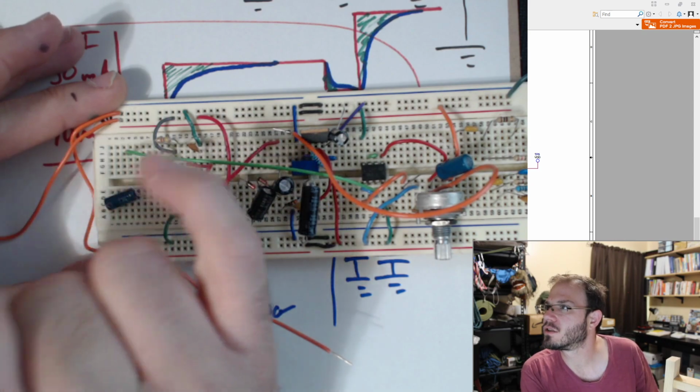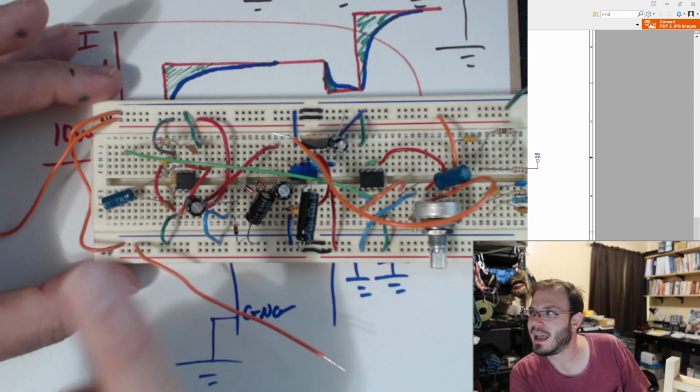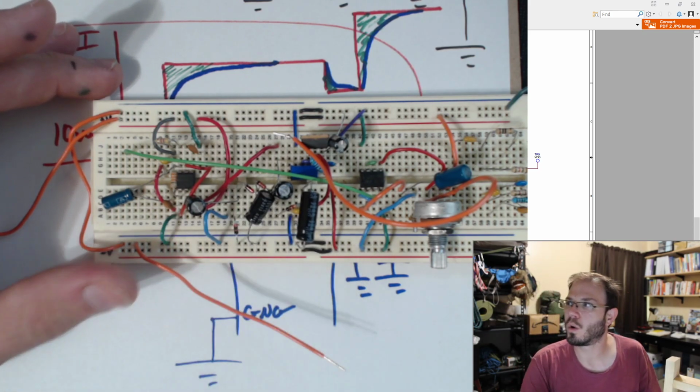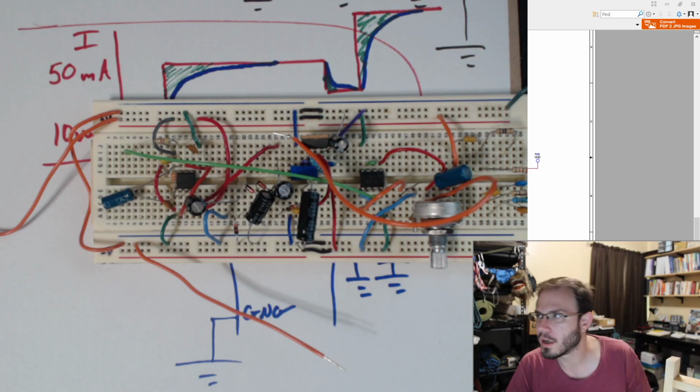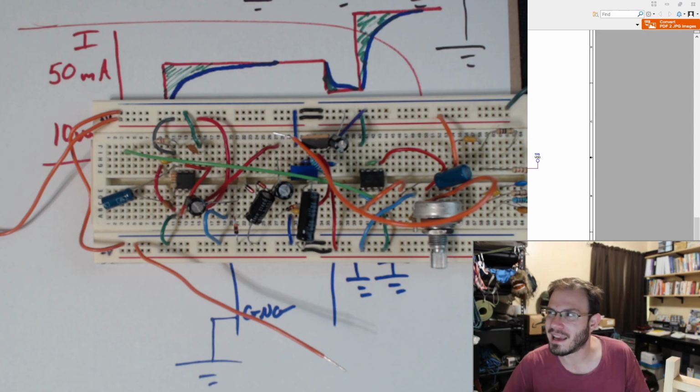I was constructing something over here, and I was measuring, and I saw that I was getting some very unwanted noise or spikes. Technically noise is random. This had a fixed frequency that I was looking at, but I could tell that it looked like there was an issue with not having any decoupling caps.